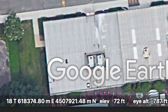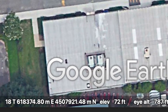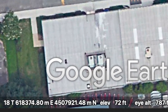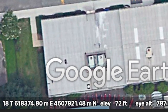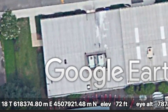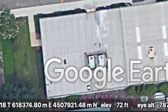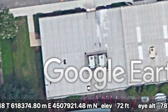And 18T is a very large rectangle that encompasses a good bit of the sort of southern New England, mid-Atlantic, Midwest region, including New York State. You can ignore the 18T. What you want to focus in on is the next two numbers, 618,374.79 meters east and 450,791.84 meters north.